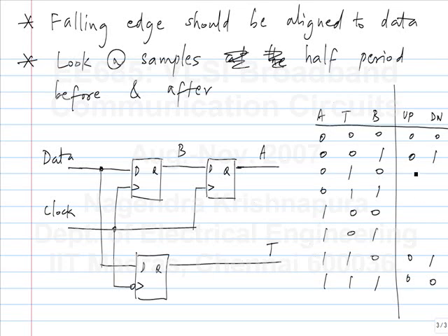What do you do with 0, 1, 0? It cannot occur, so we'll leave it as 0, 0 or something. Let's see what to do with that. What about 0, 1, 1? It's the opposite case, so you have to do this. Now, 0, 1, 0 and 1, 0, 1 should not occur really, because the data is transitioning from one symbol to the other. You can't have the symbols at the two ends be the same, but in the middle a different value. But because of noise, and maybe limited eye opening in the data, it can happen. So you can get this.